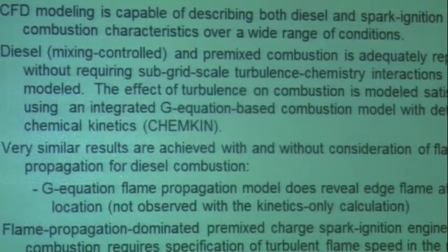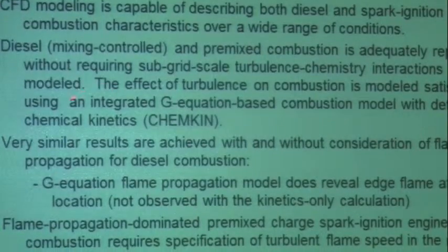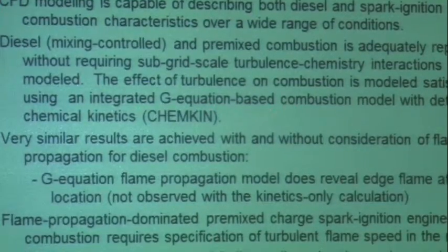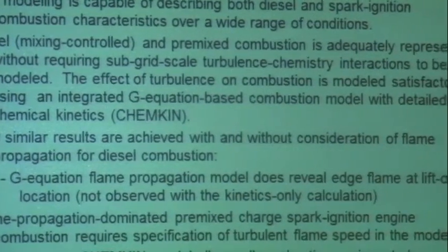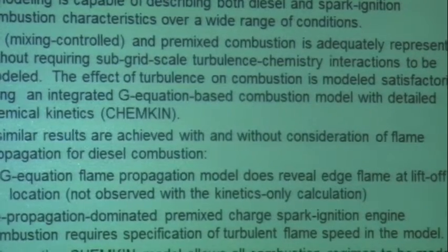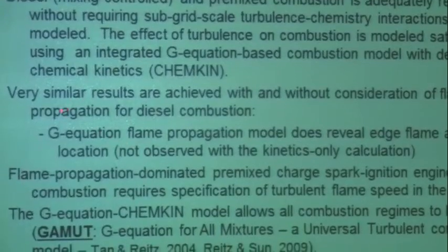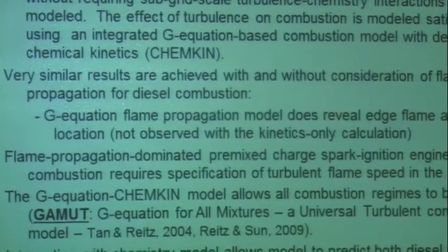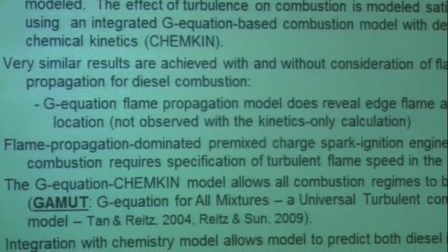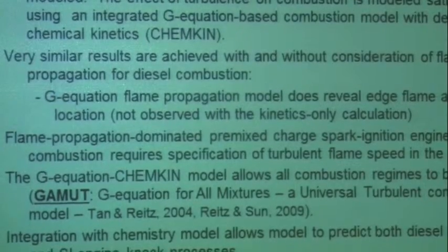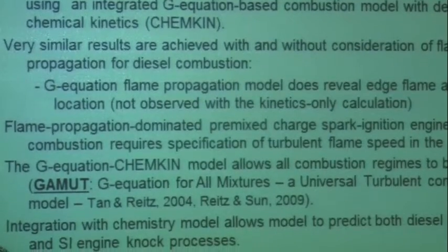The effect of turbulence on combustion can be modeled, however, using an integrated G equation-based combustion model coupled with detailed kinetics. What we saw today was that very similar results can be achieved with and without consideration of flame propagation in conventional diesel combustion.